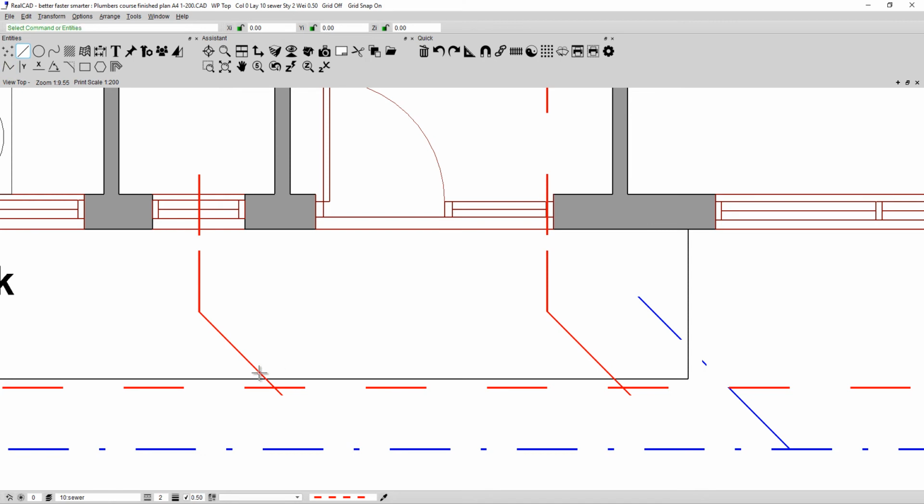So right click, trim to here, it's still active, trim this line. I have to make sure I'm past its halfway mark. You'll see the halfway mark when the cursor changes to a little dot. So there is a little dot there somewhere. Anyway, I'm going to trim here back to this line. So at least I know it's neatly in position.